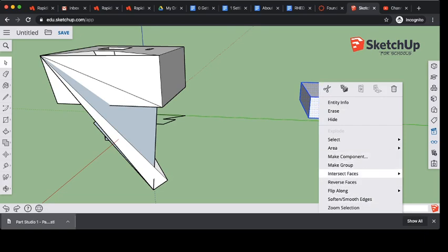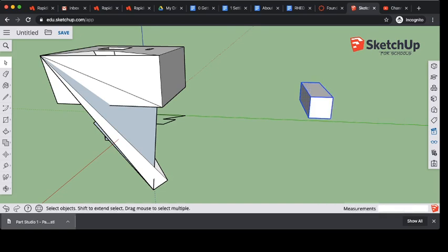A group just collects things so that they move and interact together. A component is what we would use to make parts that are designed to be reused in our overall CAD model. So I'm going to just group those together. If I select the move tool, bam, I can now move that together as one cohesive whole.